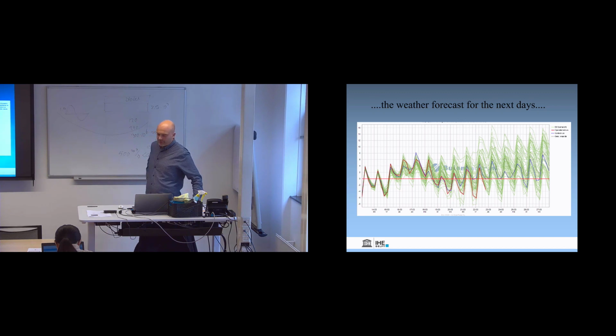And the question now is: is that also true for our morphodynamic models? Because there's so much non-linearity in our models. Already in the equations, the advection part or the friction part is non-linear, due to the power 2. And the sediment transport is due to the power 5 maybe, very non-linear. How does a system like that behave over time if you start modeling that?